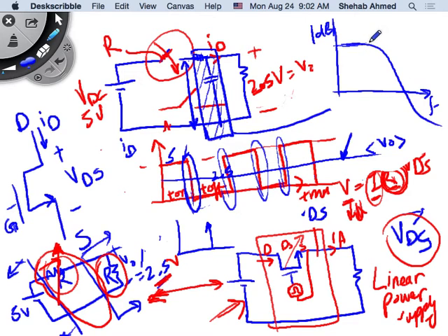So if I have a DC content, what's the average value of a signal? Remember when you were doing Fourier series, you had a periodic signal and you were coming up with three equations: the average value equation, the ANs and the BNs. You combine the ANs and BNs into a CN, which was the harmonic component of the Fourier series of that waveform. The average value is actually the DC component. The whole DC component of the signal is represented in the average value of the signal.